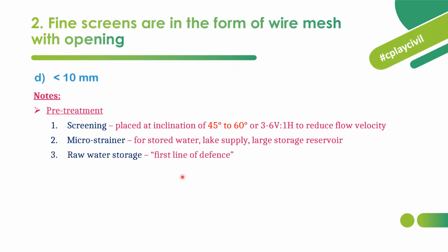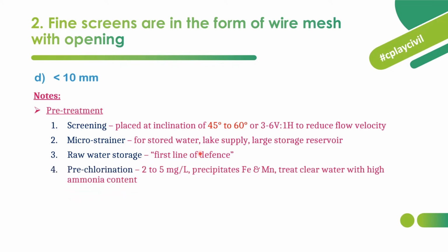And next is the raw water storage. This is called the first line of defense in pre-treatment. Whenever water is stored for a long time, there may be fungal growth. That is why the raw water storage should be pre-treated, and that is called the first line of defense.